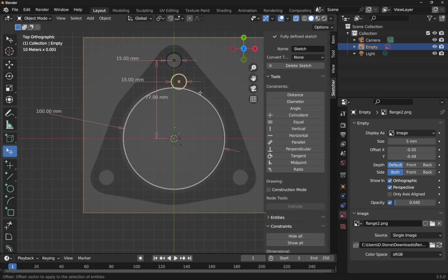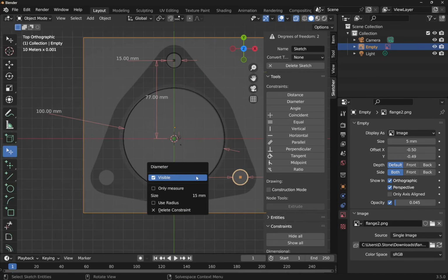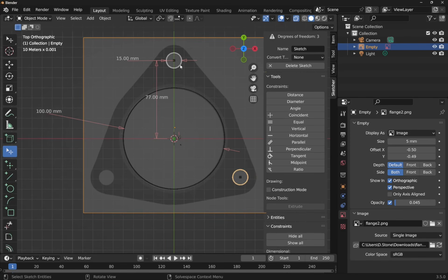We've pasted that circle now with the constraint. So I can come in and drop it in here. Best of all, it would actually be worth just clicking on that constraint and deleting the constraint, and click on this circle, shift click this circle, make them equal. So we can copy geometry across.